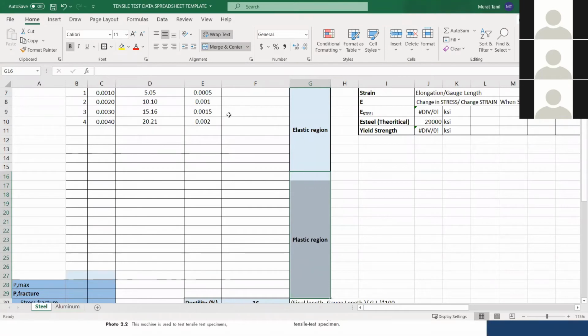In the case of, let's say, a two-story structure, you look at the floor plan, you have your beams, girders, and you have your columns. Let's say in this structure, the second floor is used for a library. In the library, you have the stationary loads, which are the dead loads. The books and the other equipment, the load is sustained by the beams, or if it's concrete, by rebar and concrete.